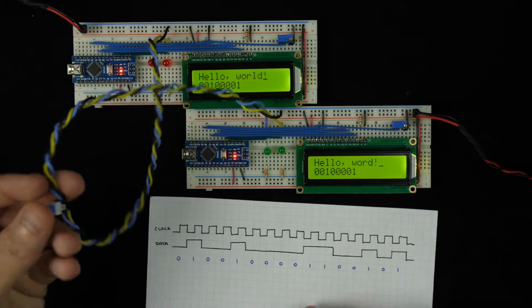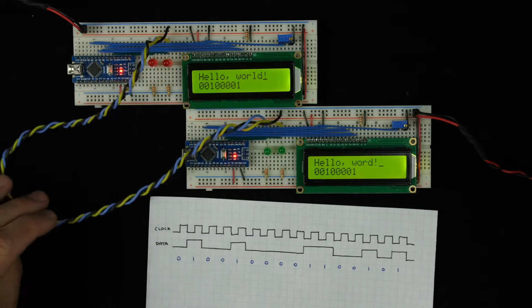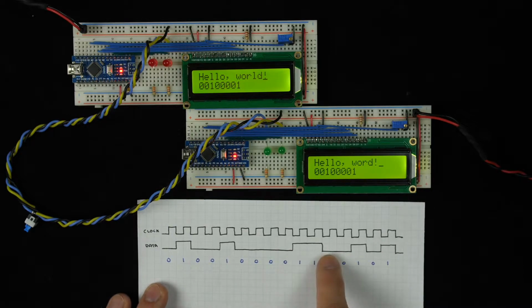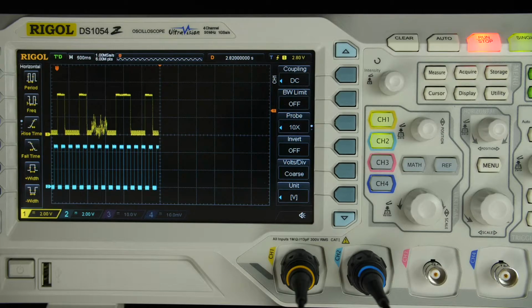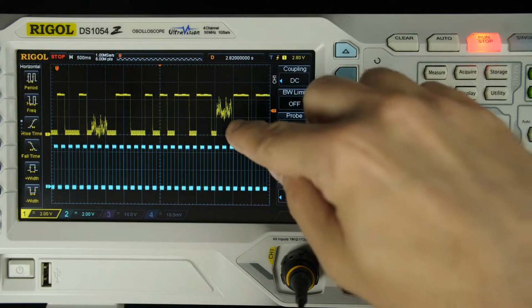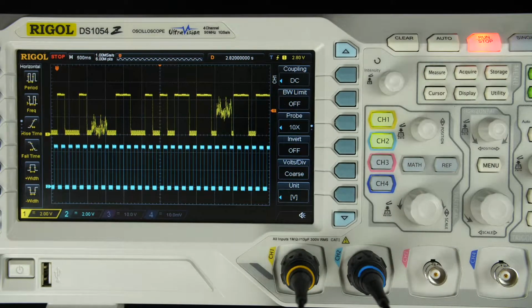So now I know I'm using this switch to artificially cause problems, but it's because it's possible for this sort of glitch to happen all on its own. So I'm showing these as nice, clean on-off signals, but really everything is analog. These are just voltages, and there's any number of reasons that occasionally this voltage might not be quite high enough to register as a 1, or this voltage might not be quite low enough to register as a 0.